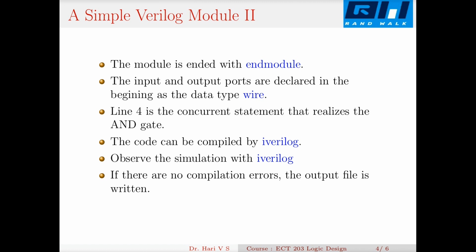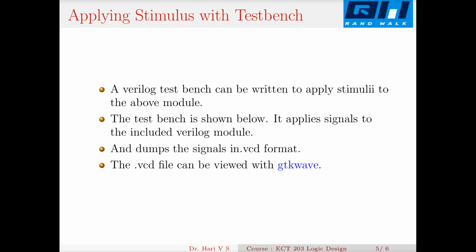Then I dump these testing signals into a file called a VCD file, or value change dump format. Then I view it with a waveform viewer. I view this VCD file with a waveform viewer like GTKWave. So that I will explain to you. So, applying stimulus with a test bench.